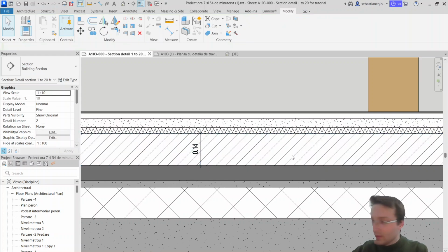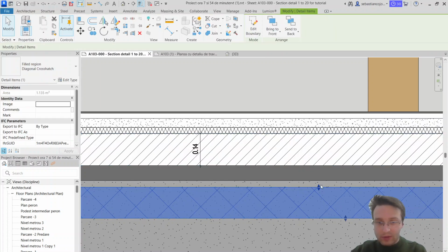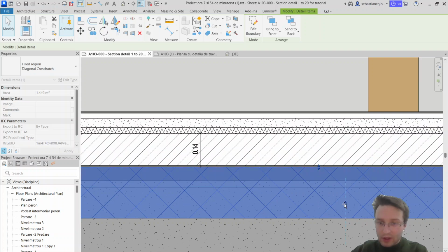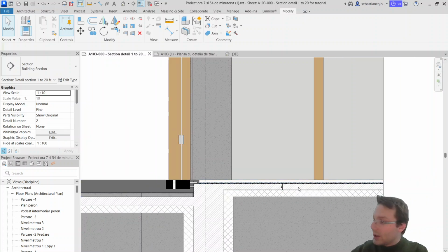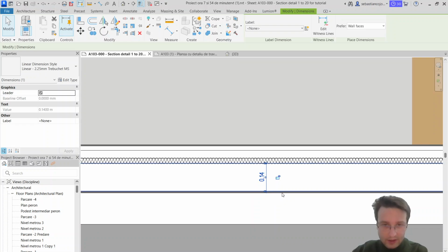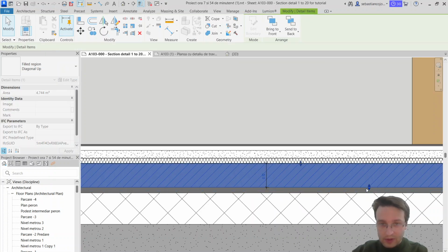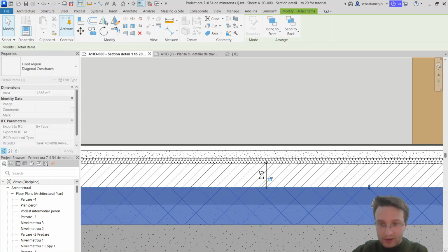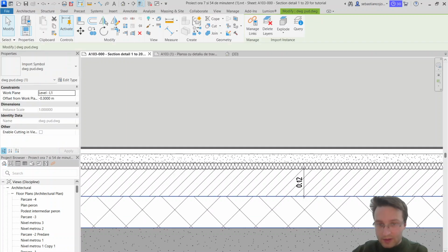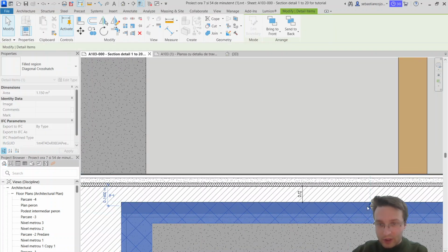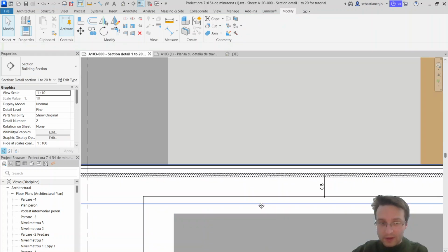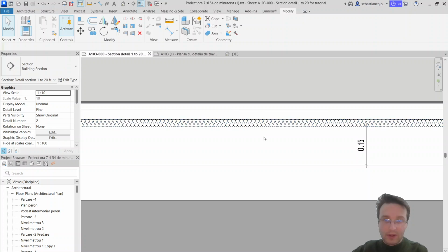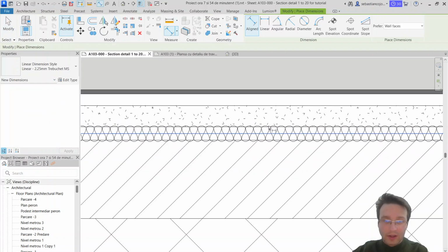Depending on the parameter, there is a formula to pre-dimension. I think it is the whole perimeter of the rectangle divided by 280 or something like that. So it's a large number divided. So it's the total perimeter, divided by a number, and that gives how thick this slab should be. Okay, let's say I have 15 centimeters. This should be 15 centimeters as well. Okay.